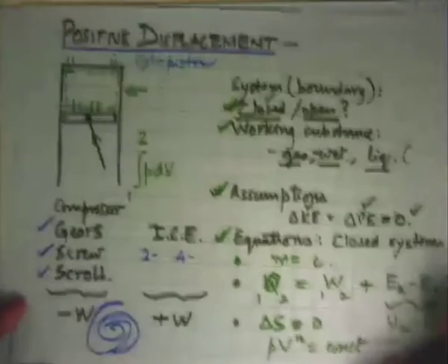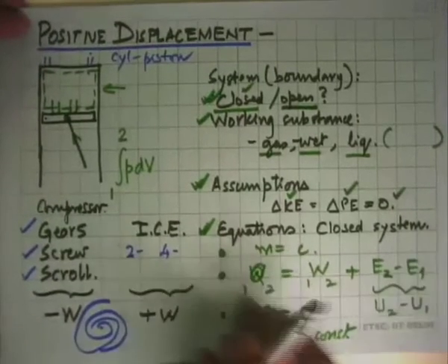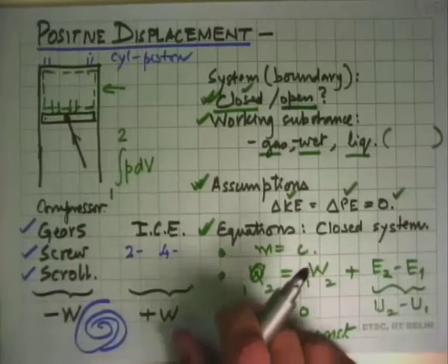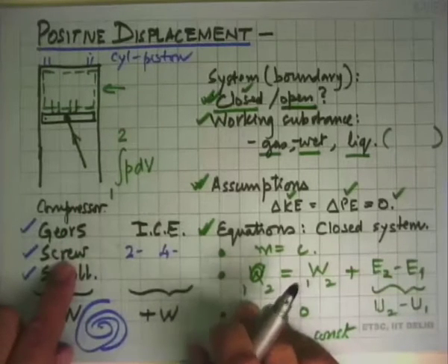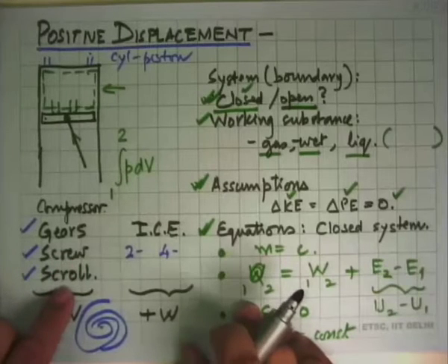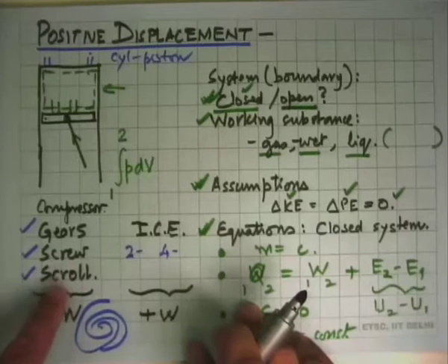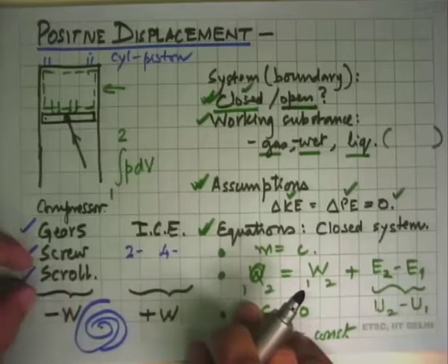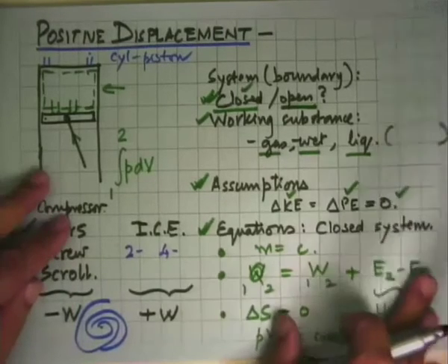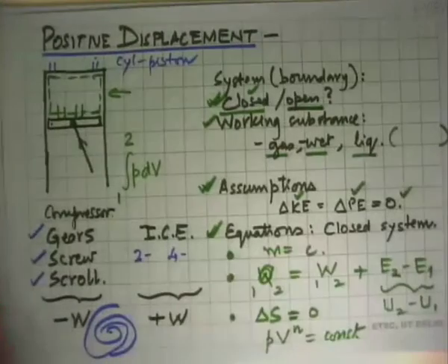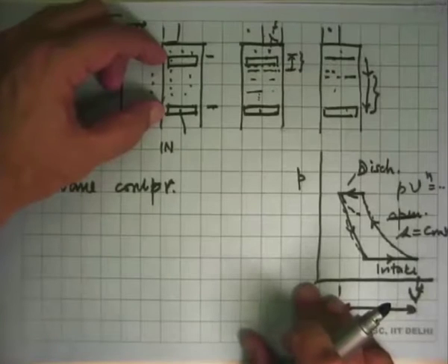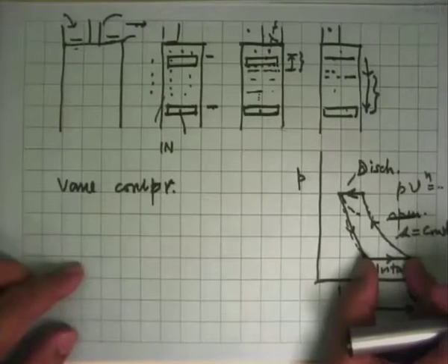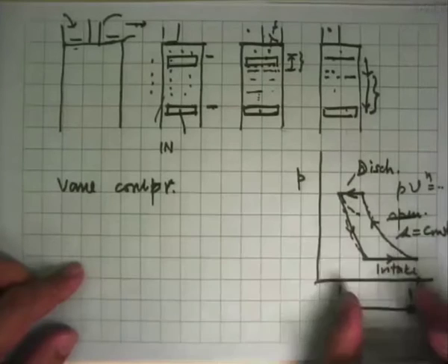And these days, the reason for bringing up this discussion is that if you look at large compressors for central air conditioning, or things where you need very high pressures in a very compact way, one is going for screw compressors very largely, and in some cases, even your domestic refrigerators or air conditioners will have a scroll compressor. The reason for doing this is what I mentioned just about how this device works: out of this much displacement volume, you are only taking in this much fresh substance, compressing it and throwing it out.